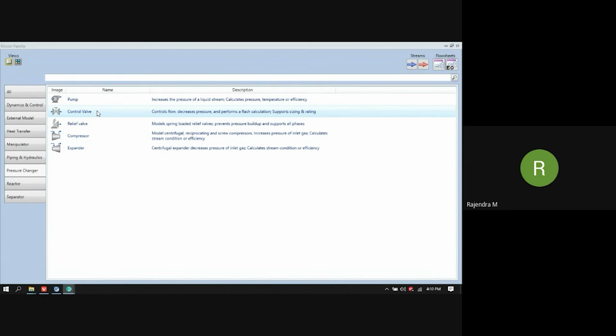the control valves, which are provided by vendors, and you have to specify the details, such as what kind of streams, what delta P is required, and what the controllability range of the process stream is. Based on that, the control valve is sized. In Aspen Plus and HYSYS, you can size the control valve based on the CV value. The sizing can be done based on the kind of output required, and the fittings in the downstream and upstream.